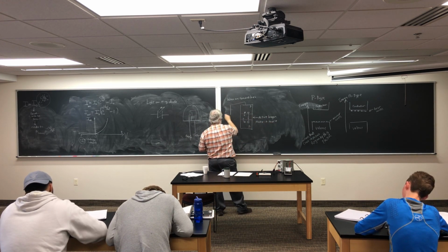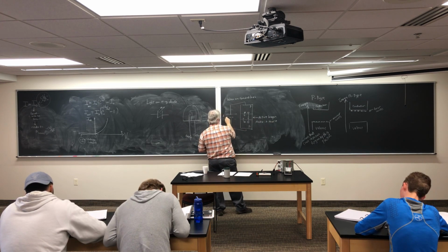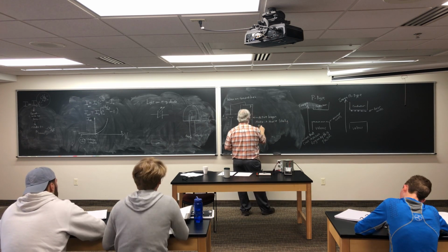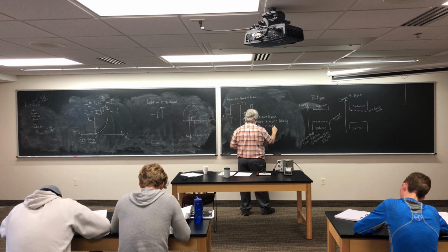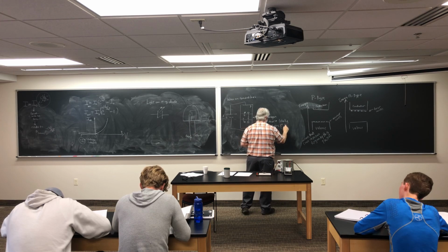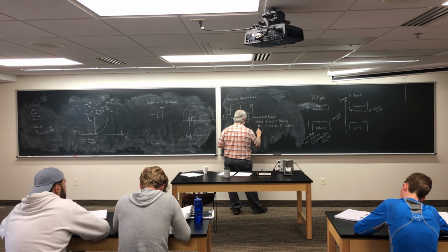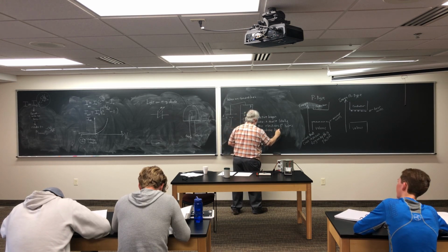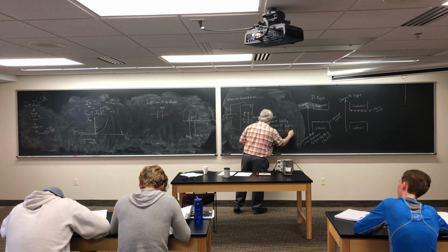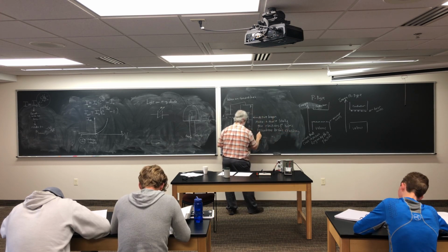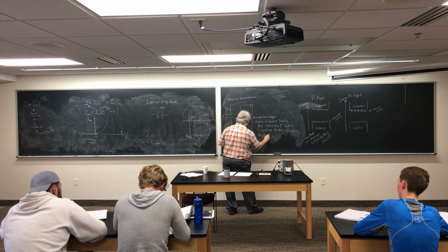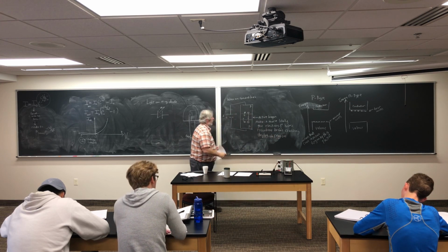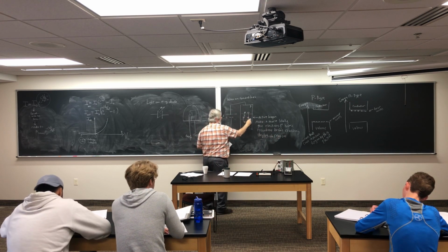So we're forward biasing, plus minus. Make it more likely the electrons and holes recombine before crossing the depletion region. So they combine in here.